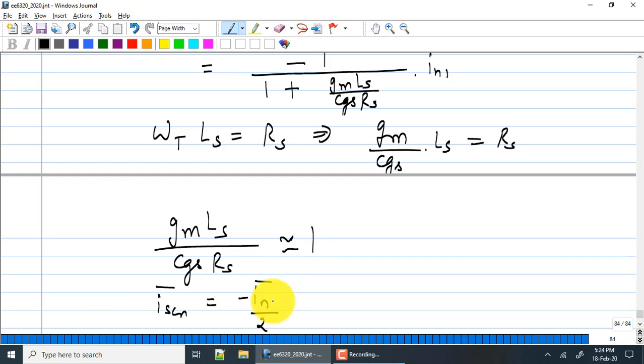Any mistakes in the equations I have done? This seems to be the simplest way I could find. Right? Have I made any mistakes? Anyway, go over it once you get back. Okay, instead of splitting the two currents, this seems easier. This is independent of frequency. Having said that, it is independent of frequency assuming that you are operating at resonance.